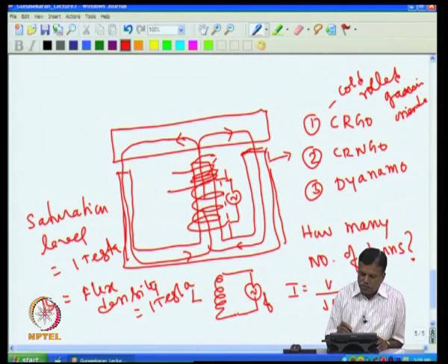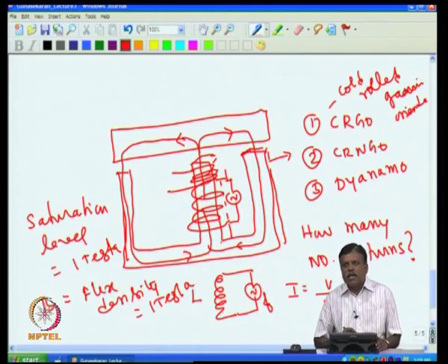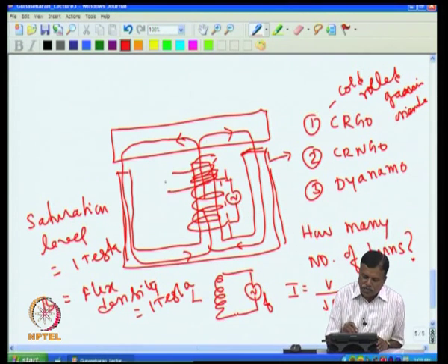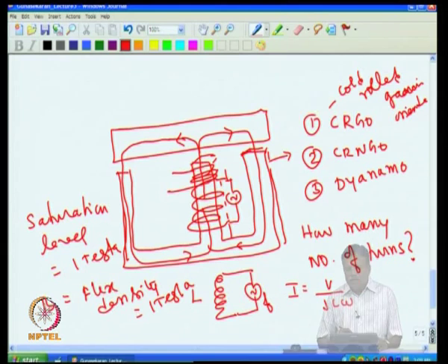So, for example, if I fix L and then go back and calculate whether the core is saturating or not, that is a roundabout way of doing it, and it is very difficult to arrive at the correct number of turns. Then we also have to check again whether the flux is saturating. If it is saturating, again you have to come back and redesign, changing L. So instead of doing it that way,